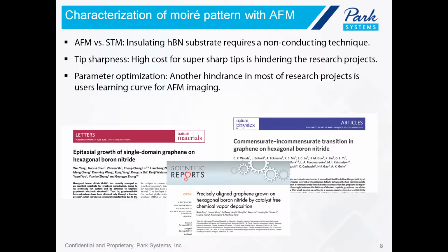Okay, so why did we pick AFM? Well, aside from the fact that Park Systems specializes in AFM, we noticed that HBN is an insulating substrate, so we really couldn't use STM in this case. We had to characterize it with a non-conducting technique. So we just used non-contact mode AFM here. The other thing that we had to keep in mind was that tip sharpness is critical here, because the sharper your tip, the higher the resolution, the smaller the features you'll be able to resolve